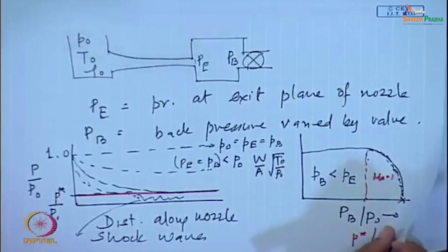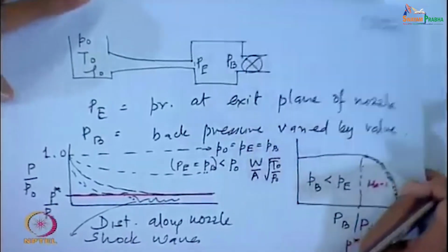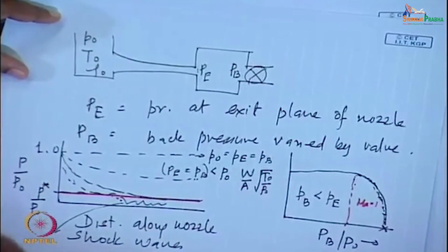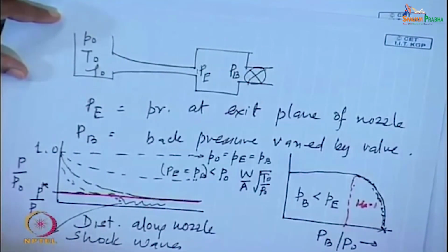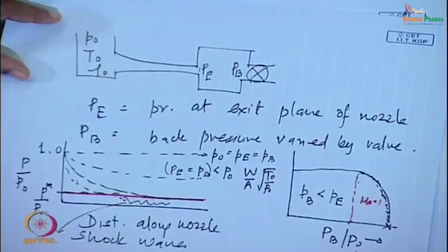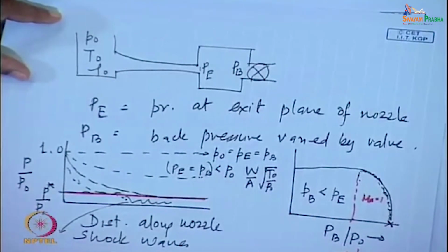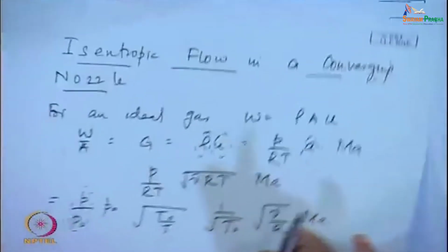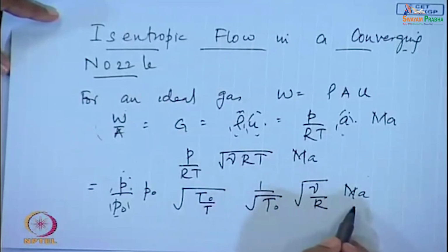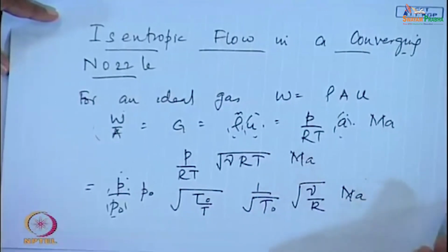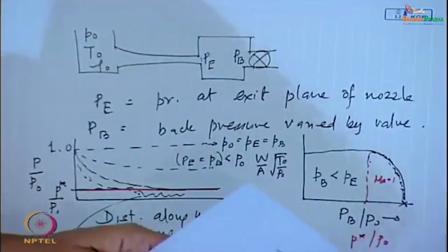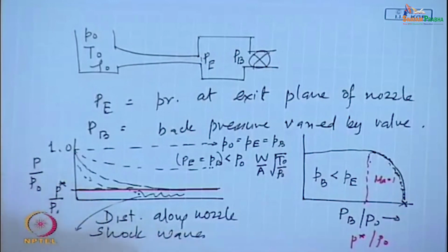For this particular case, we had seen what the flow rate will be under this condition. We had got the expression for Mach number equals W by A for maximum conditions. So, we find that for the maximum conditions we get it for Mach number equal to 1, is not it? I do not see where I had kept the final slide where I had deduced this condition.